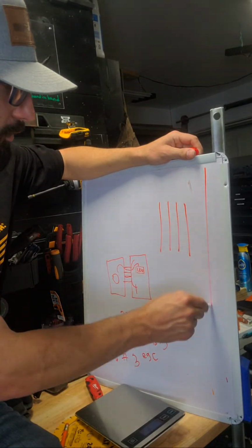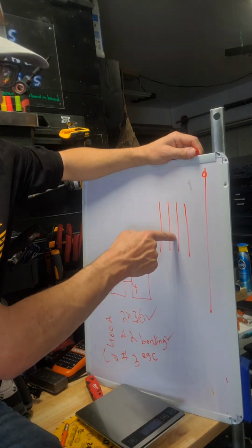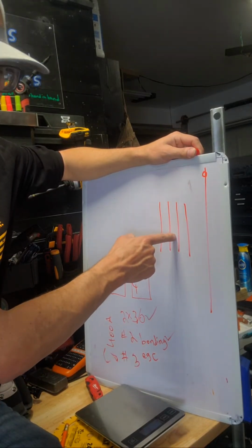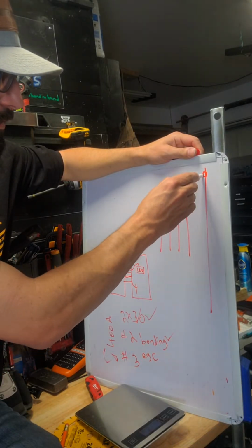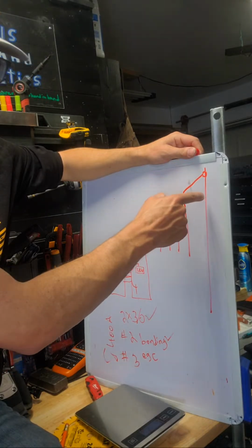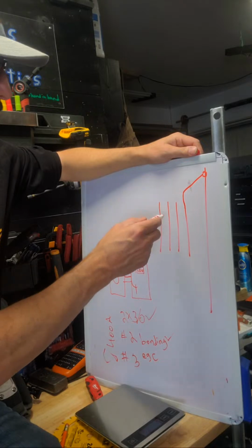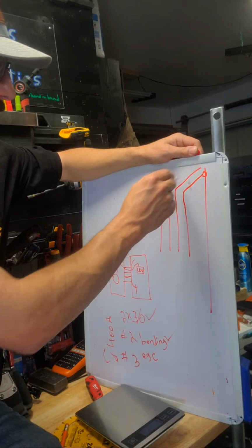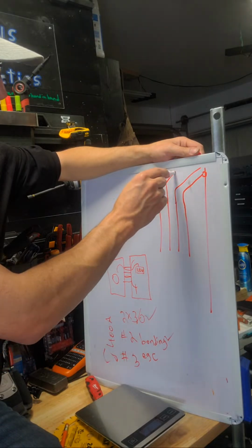And there's a wall here and you got a plug coming up here. Well, you don't want this pipe for your power to need to land over here. You need this pipe too. So you have to plan your run. If not, you're crossing conduit. You don't want to cross conduit. So when you're running your racks, you want to plan how everything's going to go. You don't want this pipe to cross this pipe ever.